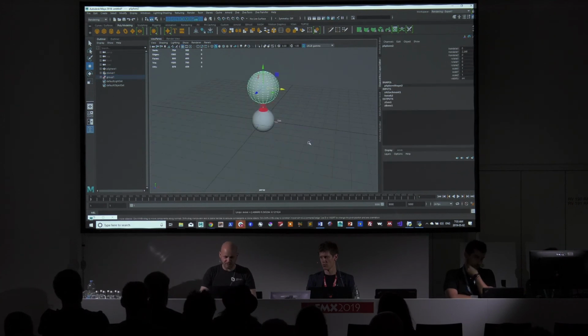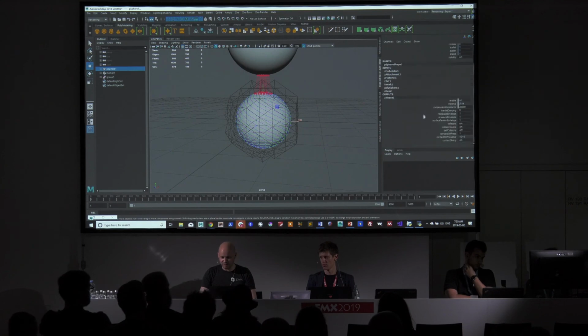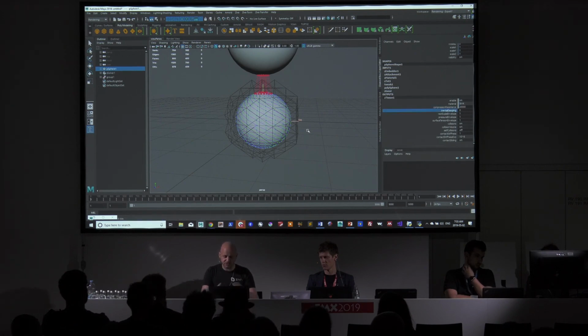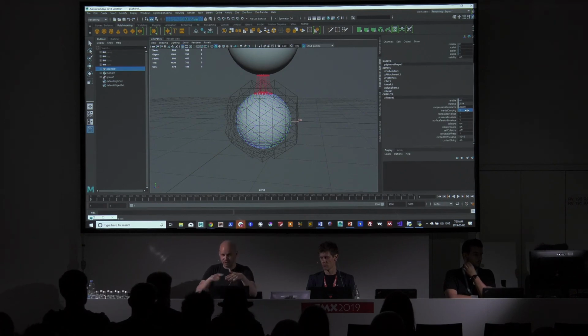I'll just demonstrate the inertial damping quick too. So per element, or per tissue, you do have this attribute on it called inertial damping, which is right there. When it's set to 0, the tissue receives the full momentum of the system. If you set it to 1, the affine modes of deformation, the things that really just relate to the position, the rotation, the shear of the object, end up getting solved quasi-statically. But all the higher frequency stuff is still fully dynamic. So what's cool with that is the object could whip around at whatever speed you want. It's not going to get any momentum. But if you whack it into something, you'll see wave propagation because it hits it.